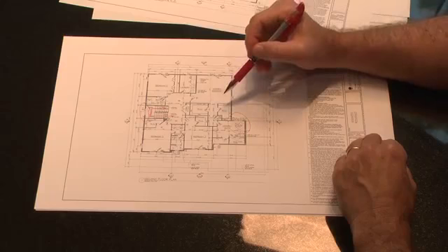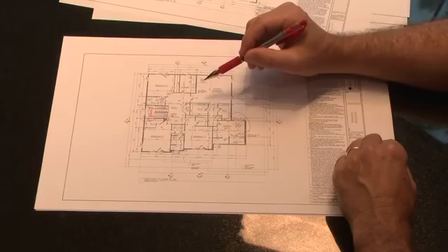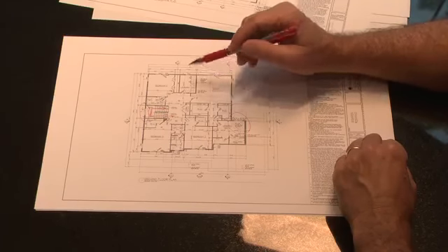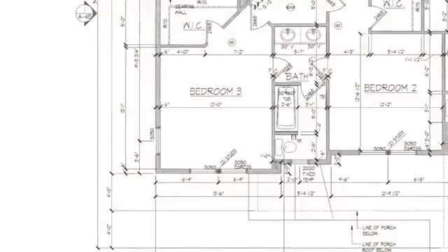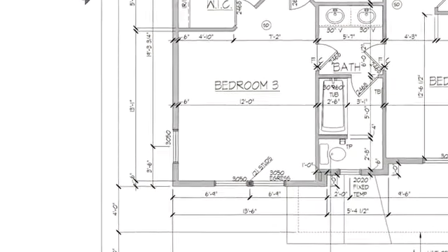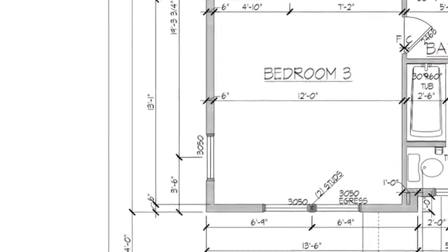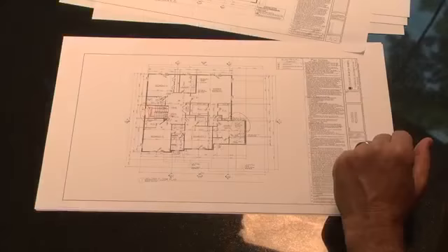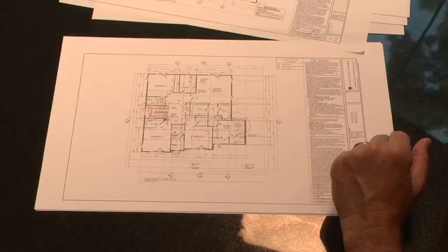On the first floor, typically we do 3060 windows. On the second floor we typically do 3050 windows. With our manufacturer, a 3-foot by 5-foot window meets what they call egress. Every bedroom must have one egressable window to meet code. And so by default, typically most of the windows are 3050.